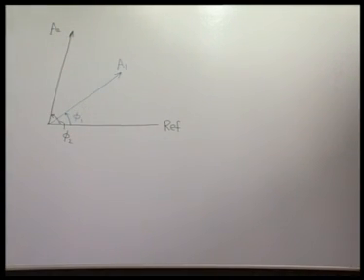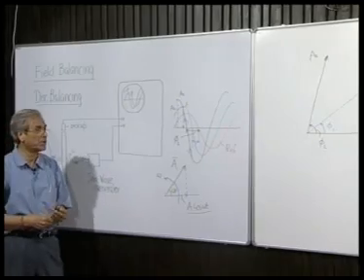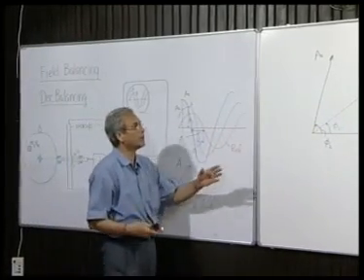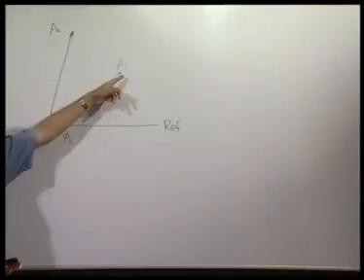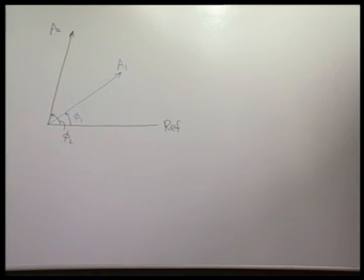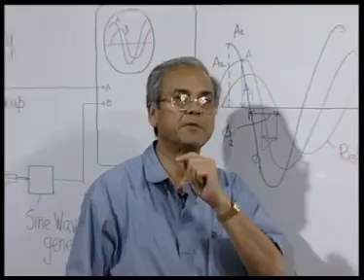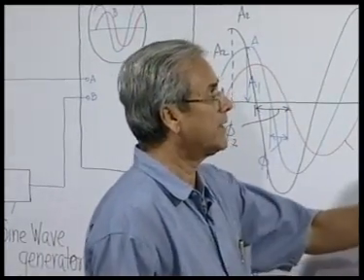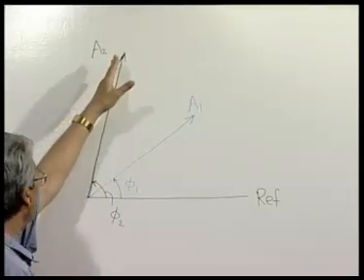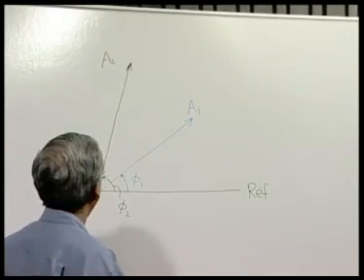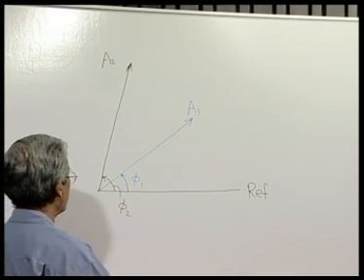Okay. So, now what we have got? We have rotated the rotor or the disc at some suitable speed to produce measurable vibration, and the vibration we get is represented by a rotating vector of magnitude A 1. Then we attach a trial mass m_t e_t and rotate the system at the same speed omega, and we get again the vibration as A 2, which is at a different angle from the reference, phi 2.